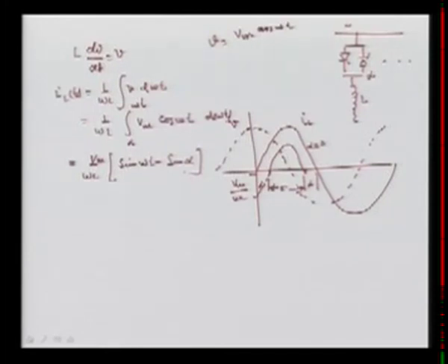So this is the current that is flowing here. There is some phase shift here. When alpha is 0, the switches are closed, or you can say it is a short circuit condition. When alpha is pi by 2, then it is open, so putting alpha equal to pi by 2 we find it is an open circuit, OC.